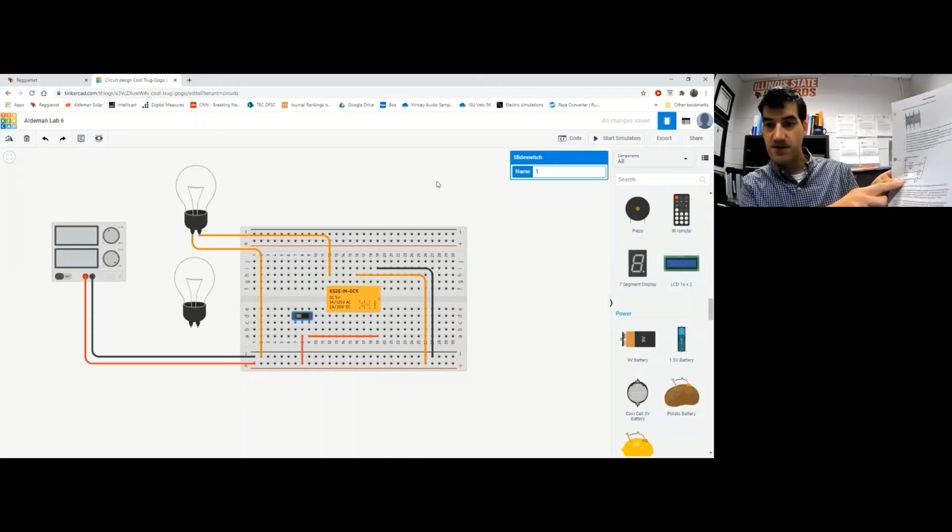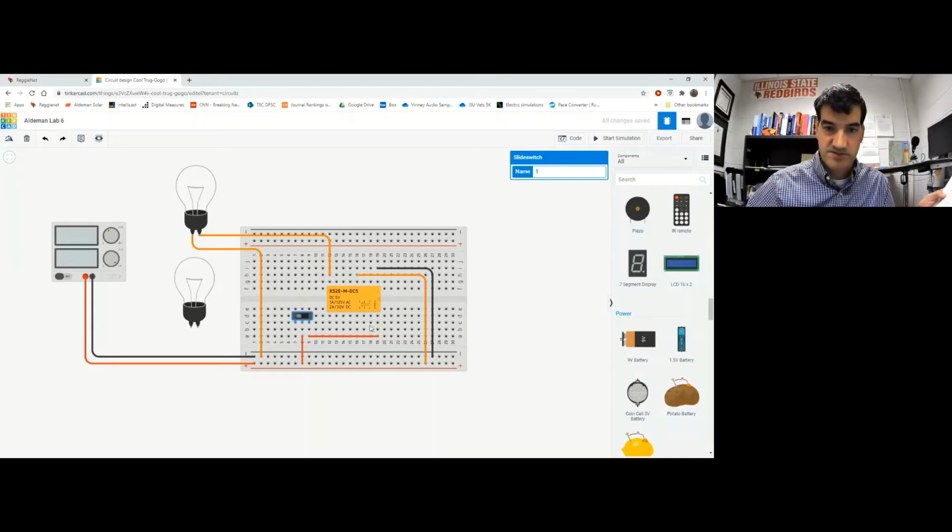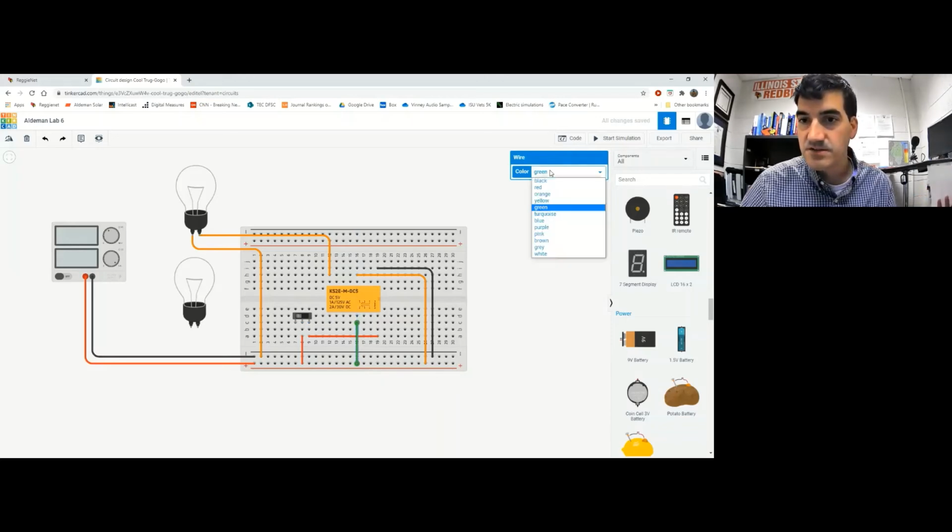The first part of the third rung means I have to go from 24 volts directly to the common of what's going to be CR1B. So I'm going to go from 24 volts, that's this rail down here, to the common, and this time I'm going to use the other common, which is terminal 13. So I need to go from one of these to the positive side right there.